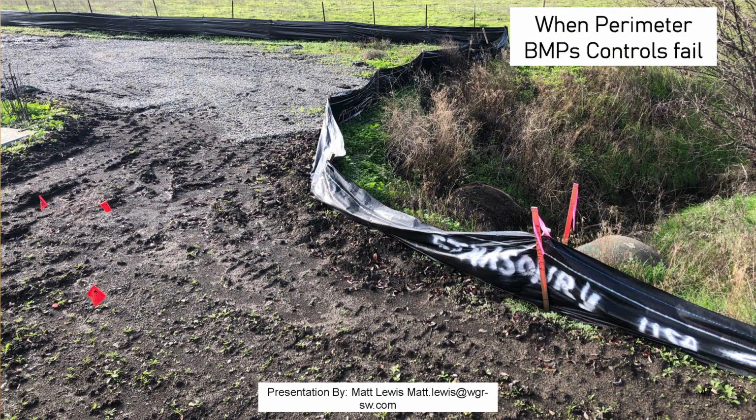And so at another portion of this site, there's a little bit of erosion that's coming down, just slipping under the silt fence. So this is the kind of thing you're going to nickel and dime your contractors about all the time. Silt fences not being keyed in, fiber rolls not being keyed in. Those are probably the two things that you're going to see the most: not proper installation or proper maintenance.